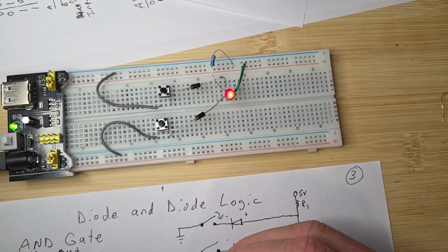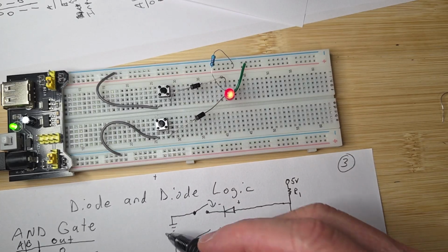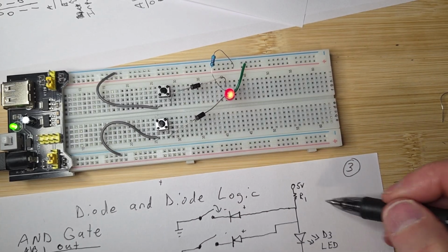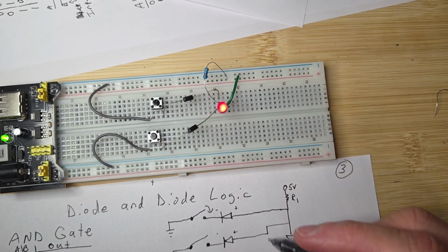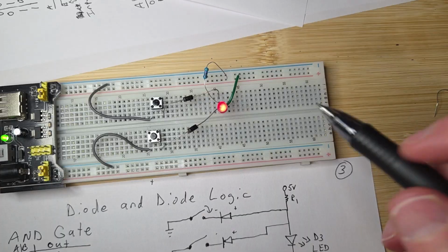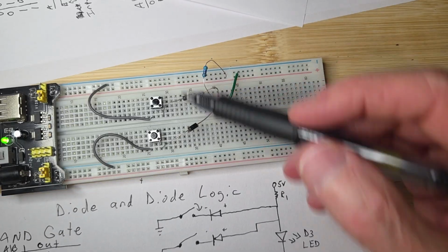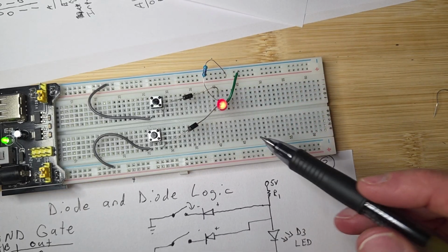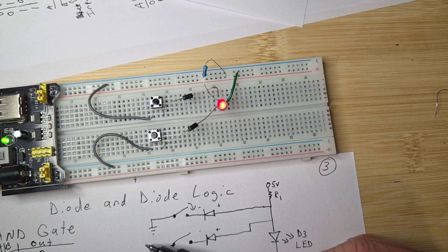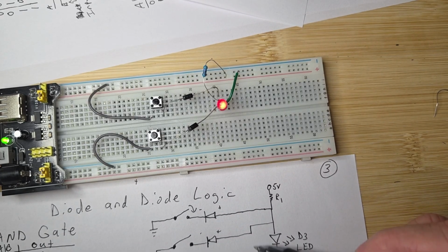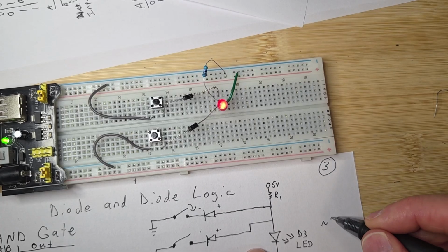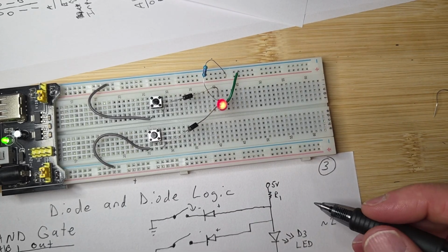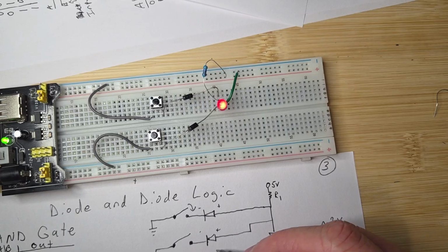So it's a little different this time. We're going to ground this time. Remember, ground is 0. It's a pretty simple little circuit. The way it's set up, since these are grounds, when we put 0 0 on here, these diodes are going to short across the LED. The LED takes approximately 2 volts to turn on, while these only take like 0.7 volts.